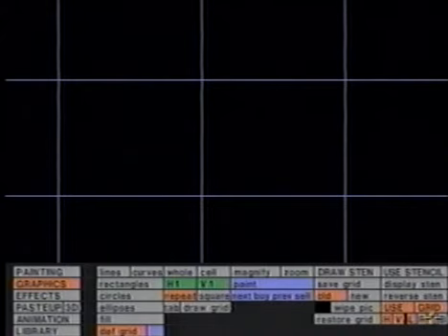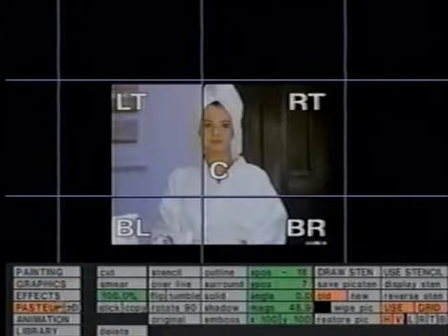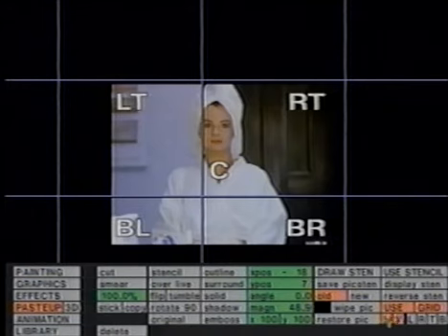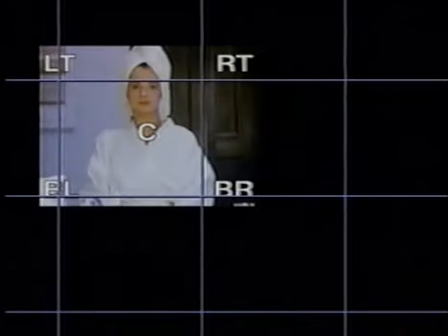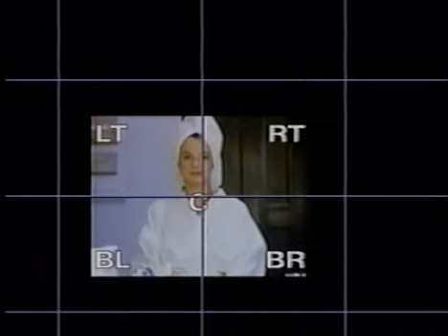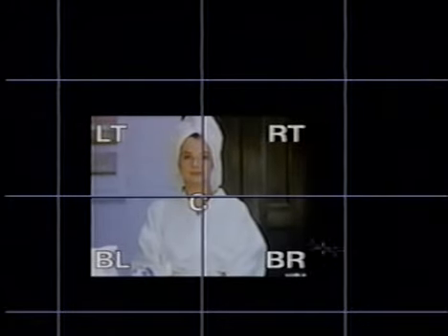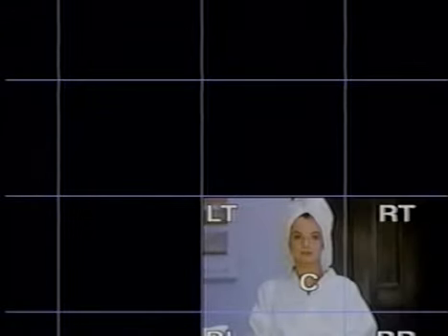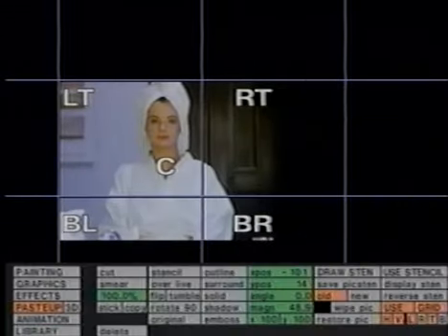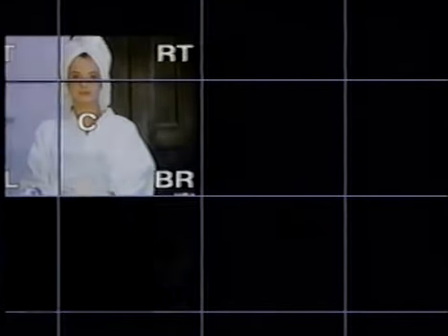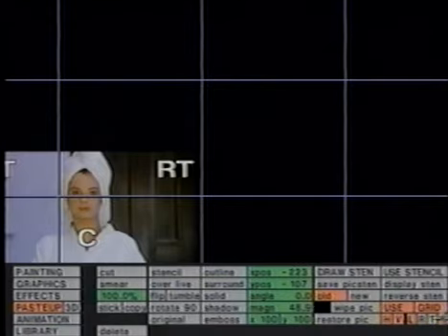With Use Grid on in Paste Up, there's a choice of how the cutout is to be aligned. This is set using the boxes, so with left, right, top and bottom boxes off, the center of the cutout snaps to the grid intersections. With L and T selected, the left top corner fits the grid, or R and B for bottom right. Or single boxes can be selected, such as left only.